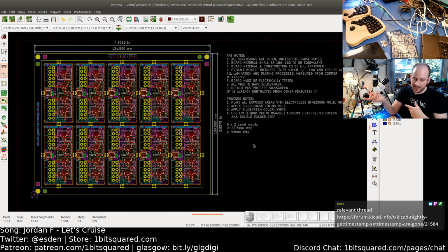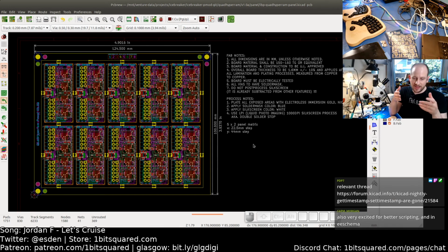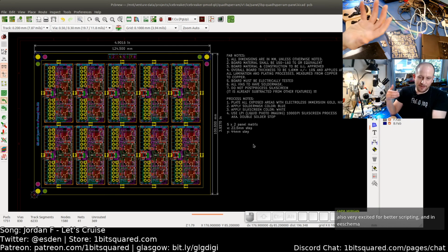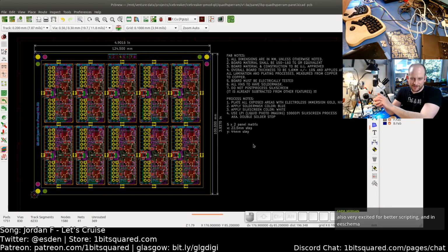UI integration. For example, what would be nice for scripts like the script that Greg did for length matching, it could show the results of the length matching directly in the UI of KiCad. That would be nicer than running it in a separate terminal, because how Greg does it, he currently loads the KiCad file separately in its own script and measuring the lengths and then outputting the changes, monitoring if the file got saved or changed, and rerunning that script. It would be nice if it was a part of KiCad.